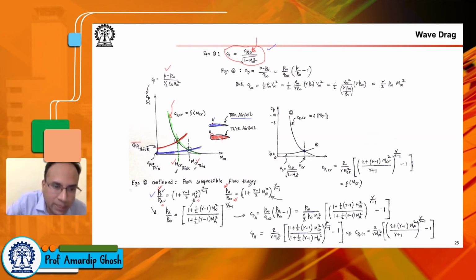So this becomes a bit tricky. You have to justify that point. But we are just trying to find the critical Mach number, and we don't have shock waves in the system up to this point. Then you can say that your P naught here and P naught here are the same. So if you divide these by each other, you get static pressure at A divided by static pressure in the free stream, given by this relationship, where M infinity is the free stream Mach number and MA is the Mach number at point A. This follows just from this expression.